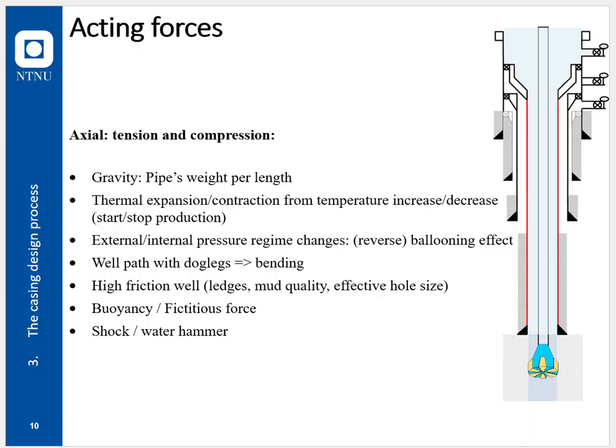That would be like a shock. The Joukowski equation rules shock going through a system like that. When you're pressuring out, say, a plug in the well, that you're cycling out a plug, and then suddenly the pressure is released, you will have a water hammer effect.